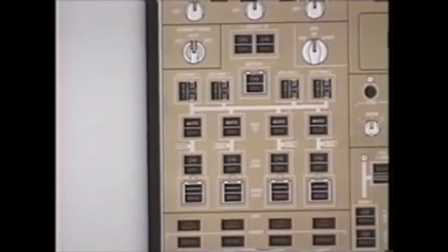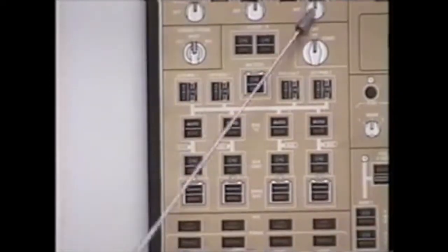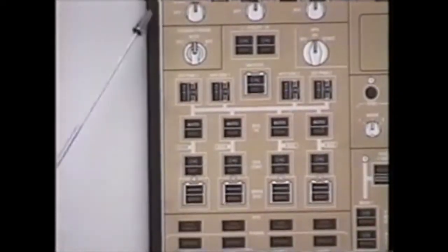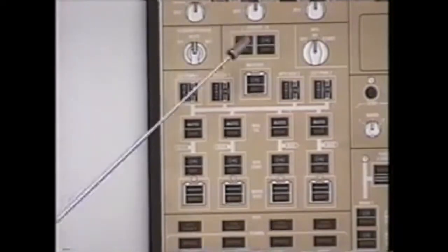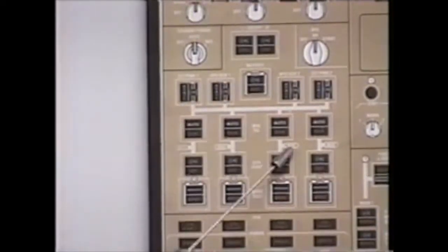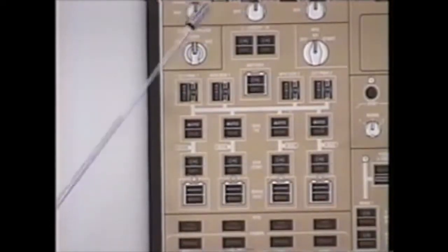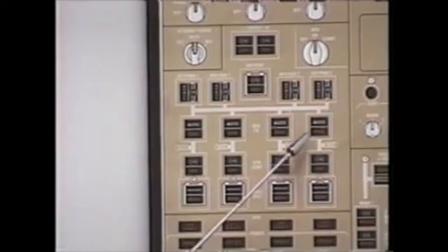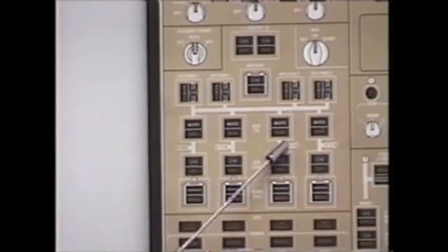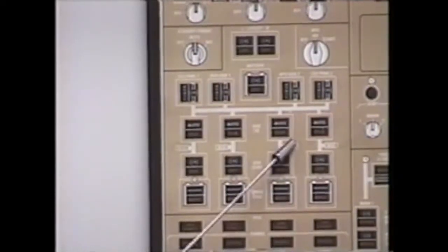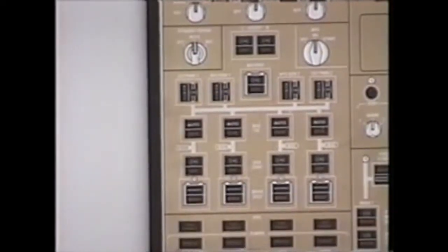Moving down and below the IRS control panel is your electrical control panel. Several switches on this panel. We'll start with the utility switches left and right. Attached to each AC bus are 2 additional buses called galley and utility. They're attached to that respective AC bus through load controllers. If an AC bus is overloaded, it will start load shedding the galleys first, and if the power requirement is even greater, it will then shed the utility, repowering in reverse order.